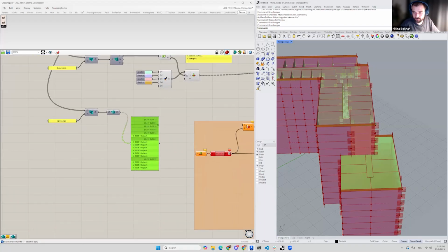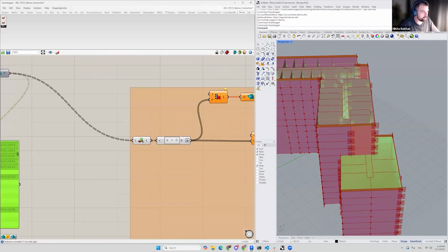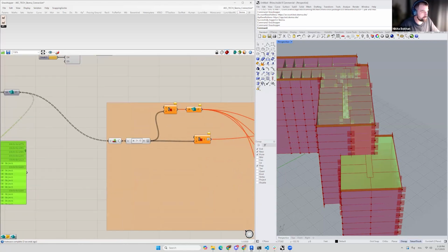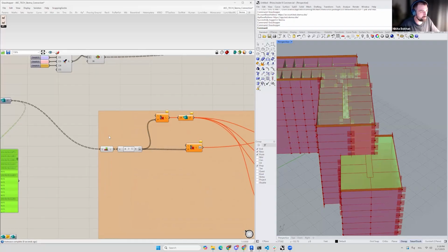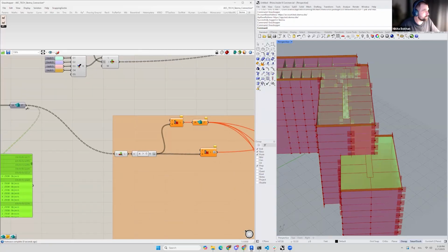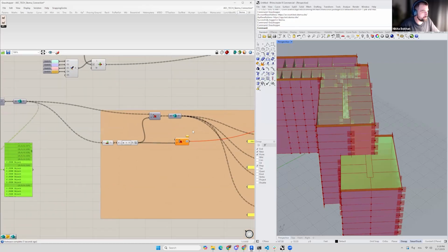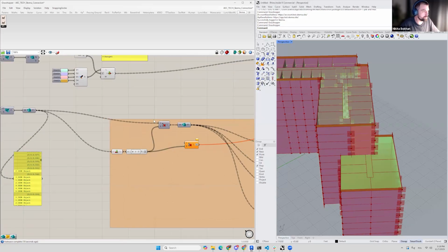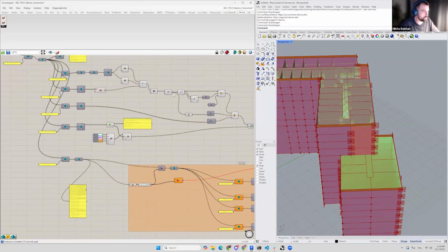And here I need to filter them. This is why I use these predefined components you can find. I essentially search for a list with a length of 0 and get rid of all the empty ones. And here I need to provide my actual walls, the lines where I need to allocate my windows. These are my polylines.